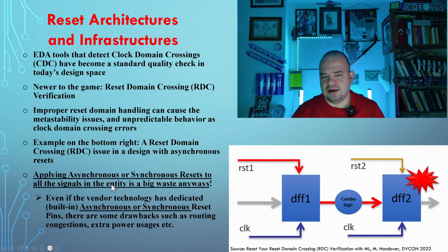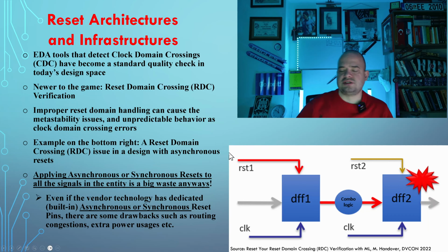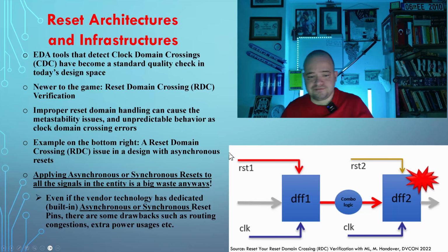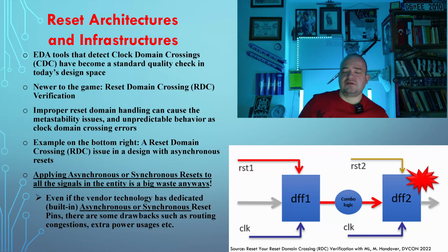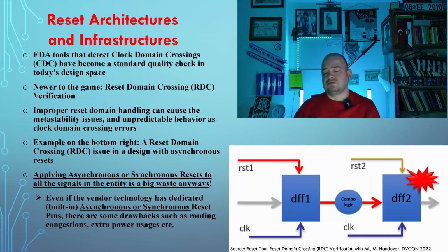Applying, again I am mentioning, applying asynchronous or synchronous reset to all the signals in an entity is a big waste anyway. As I mentioned, you need to check your vendor technology, your FPGA device guidelines, and you need to be aware of whether you have built-in synchronous or asynchronous resets.